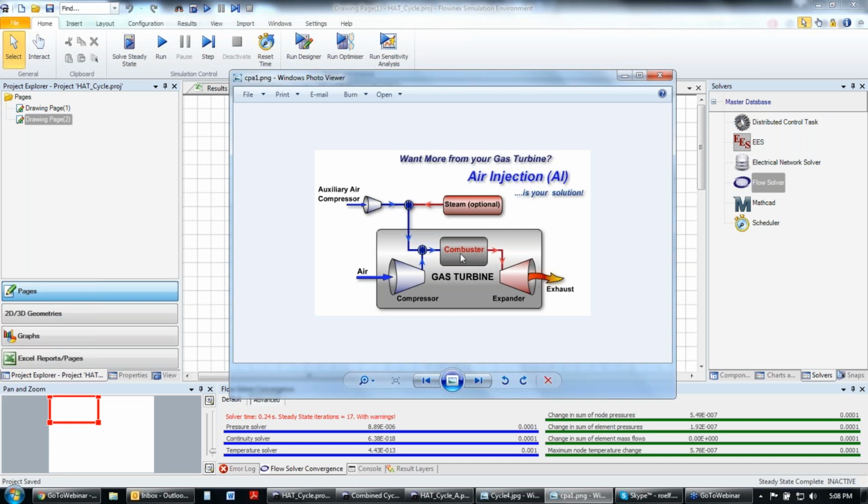So in order to cool down the flame temperature, we need excess air through our compressor. And that needs a lot of power to compress in order to get it through the system. So the engineers come up with a lot of ideas to create better ways to have higher system efficiencies. One of them is to rather include water into our system and thereby save the energy that would have been used to compress all of the air and to have the excess air. So that is an overview of what all of this is about.